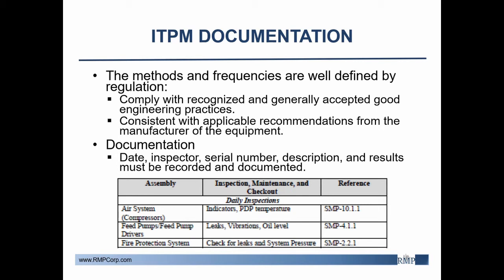Facilities often maintain these electronically as they're easier to access. And generally, we see facilities use the most conservative estimates of these items, whether it's the OEM manuals or other standards, in order to determine the initial inspection frequency of their equipment, and then from there they can use operator experience in order to make it less frequent and more practical. NDEP's guidance states that the frequency of preventative maintenance must be determined to be the most conservative of vendor recommendations, best engineering practices, or operating experience. This means that both OEM manuals and applicable standards must be on hand to provide evidence for conservative maintenance frequencies.